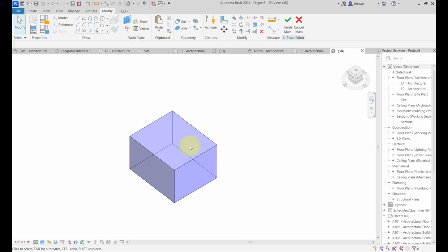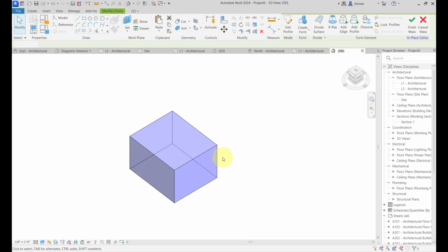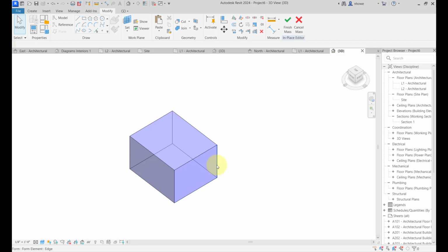So now let's talk about what's the next level of complexity. Not only can we model or move these various lines to get something very unique, but then we can start to model more things into this. So you see the set working plane. We can always set the various reference planes that we already have. So east, west, level 1, level 2. Apparently there's a reference point.